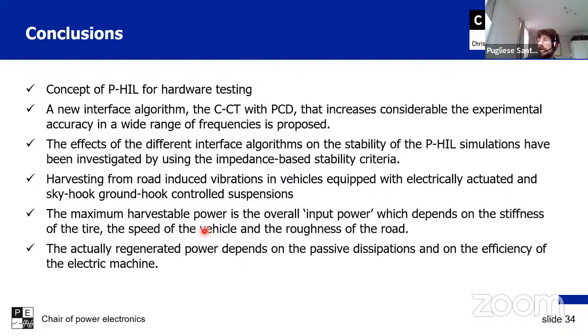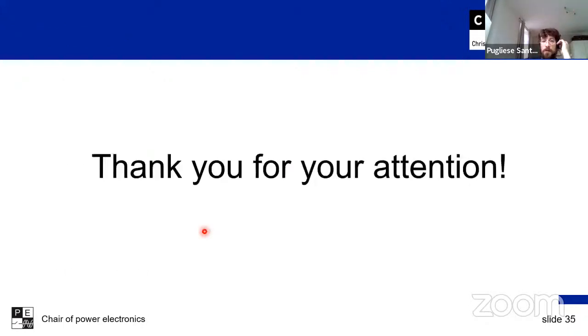However, we can regenerate, and as I said, we can use it as a possible input at the DC bus of our battery stack, in order to identify the state of charge and the state of health of the battery, and doing some impedance spectroscopy test. So, from here I conclude.